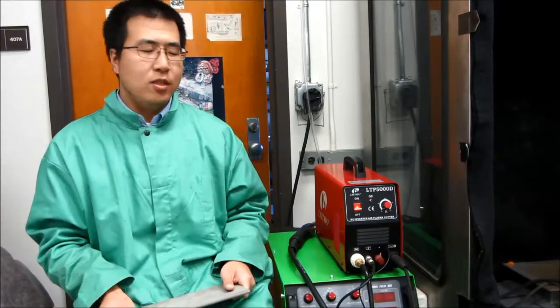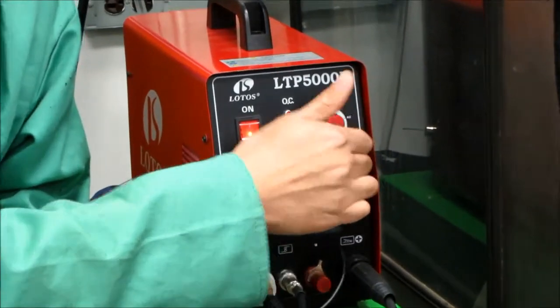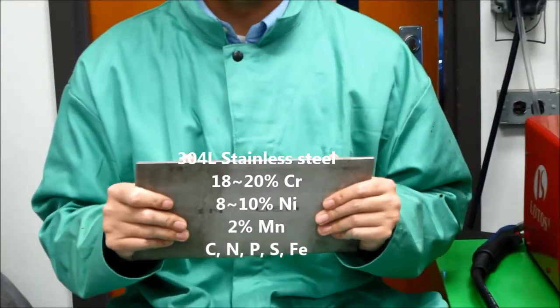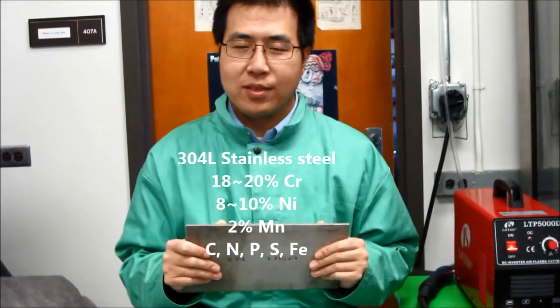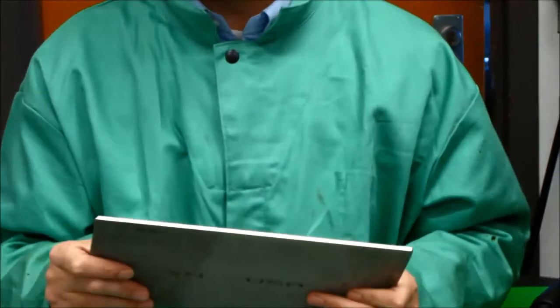In this study, we are using an inverter plasma cutter with the arc current ranging from 20 amps to 50 amps. The stainless steel plate we are cutting is 304L stainless steel. It contains chromium, nickel, manganese, carbon, nitrogen, phosphorus, sulfur, and iron. The thickness of this plate is 3/16 inch, and the cutting time ranges from 5 seconds to 30 seconds.